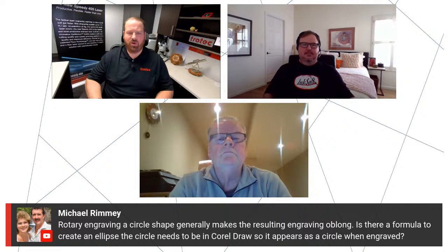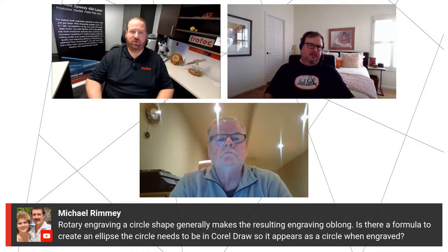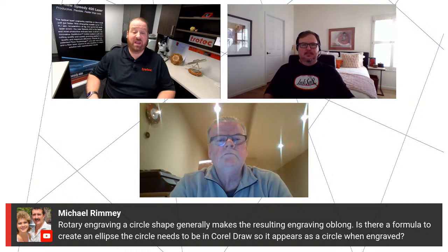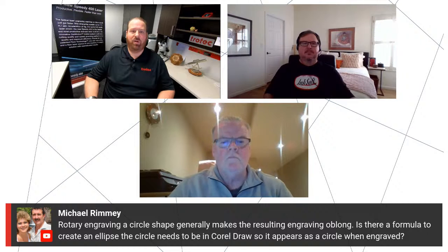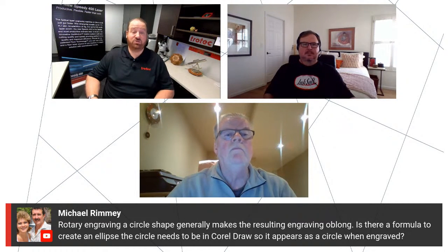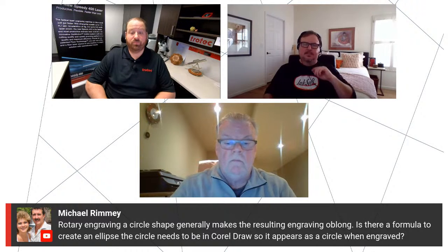The rotary, if you put the right diameter in when you're using your rotary, you'll get a perfect circle every time, unless you've got a lot of taper on your glass or your tumbler, for example. But in most cases, you won't see that. If you're getting an ellipse when you engrave on your rotary, most likely that means you're not putting in the correct diameter, so it's not rotating that product correctly. There's nothing you need to do in CorelDRAW. You just need to make sure you measure your diameter correctly where you're going to engrave, and it should rotate properly to give you a perfect circle.